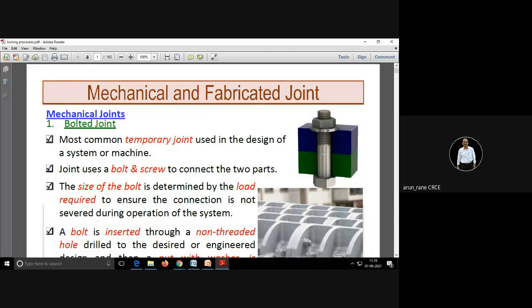Like suppose if this is M10, let us call this an M10 bolt. Again, many of the students fail to tell what is M10. M stands for metric and 10 stands for the diameter of this bolt. Generally the threads are designated like this, M10 by 1.